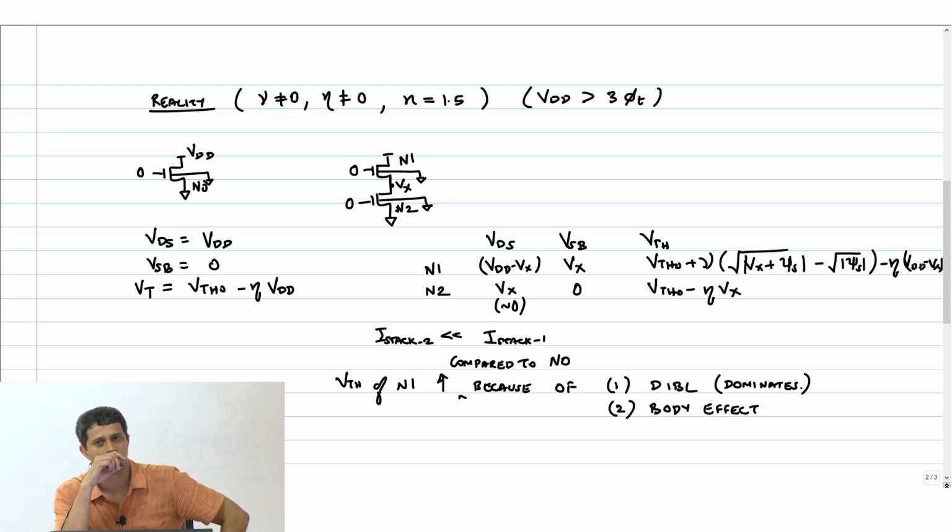Okay. So any questions here? You can refer to that paper and go through that whole derivation. It's a very interesting derivation. The key point I want to convey here is, if you just take a long channel device without all these short channel effects, then you will not get that much of a saving. It comes because of all these short channel effects. And of course, leakage itself became a problem only because of short channel effects. So you have to use it only here. You don't have to use it in a long channel device.